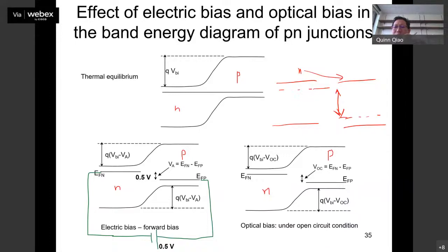My question is that if the two electric fields are both there, the depletion region electric field as well as the electric field generated due to the segregation of charges at the grain boundary, which will be more dominating? Will the band bending be there or not?